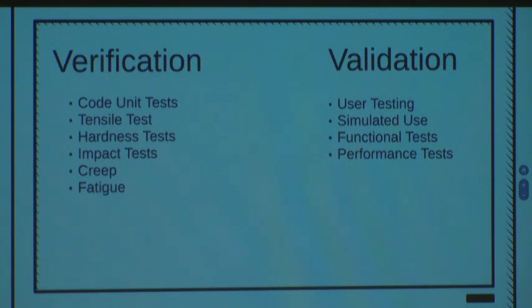Likewise, validation testing tends to be user testing. Some other good options would be simulation. So sometimes you can't do a real test. When we would do validation tests in the medical device industry, we'd usually use cadavers. So we would do lots of verification tests on mechanical test equipment.